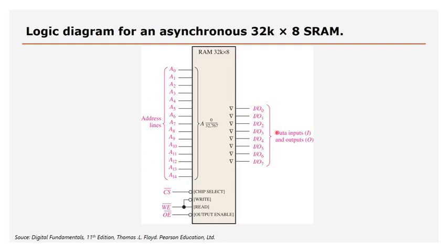If you look at this data bus and we talk about outputs, that means data will come from a specific position again, which is decided by this address bus here, address lines that specify the position, and that data will then be pushed out to the data bus and it will become outputs. So we can either read data into the device or we can push data out of the device. Let me rephrase that. I can read data from the device or I can write data to the device.